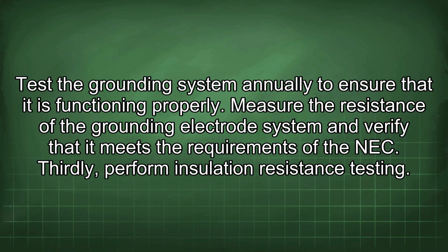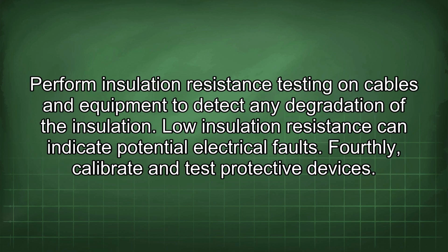Thirdly, perform insulation resistance testing. Perform insulation resistance testing on cables and equipment to detect any degradation of the insulation. Low insulation resistance can indicate potential electrical faults.